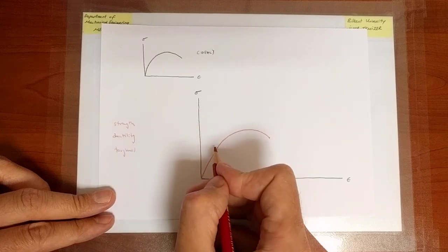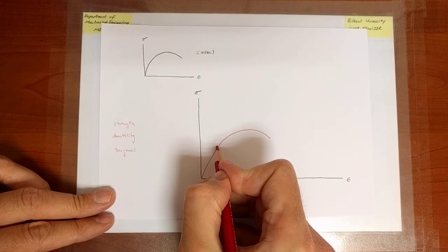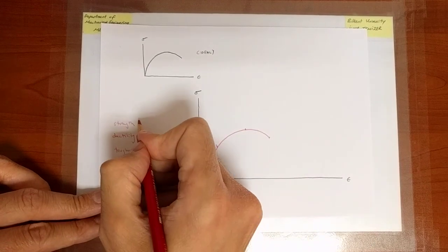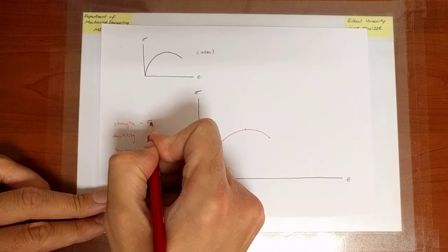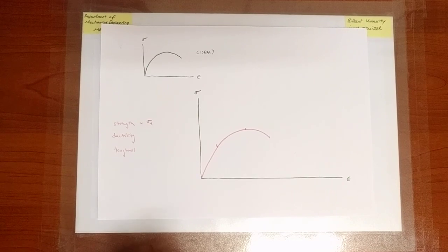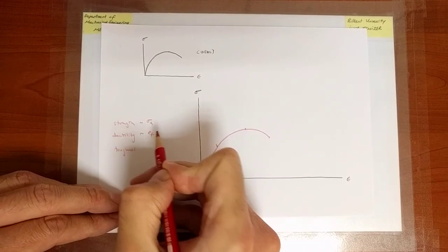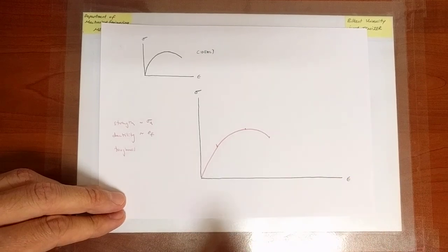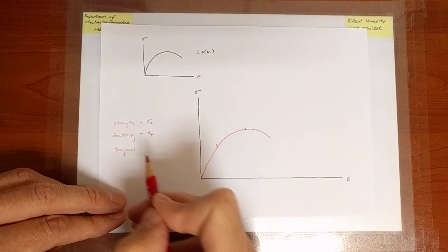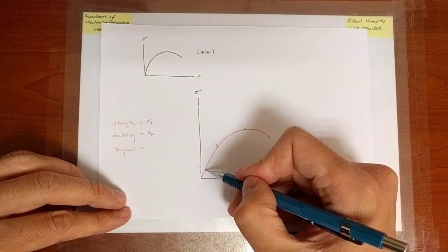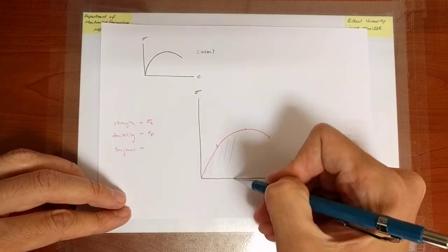Well, it might refer to the yield strength or the ultimate strength of the material, but let's say that it is eventually and more practically relevant for the ultimate strength. The ductility is associated with the fracture strain. Okay, that's our fracture strain. And toughness has to do with the area under that curve.